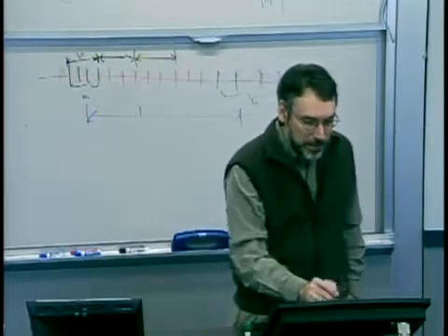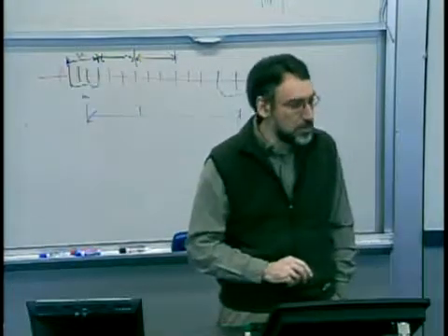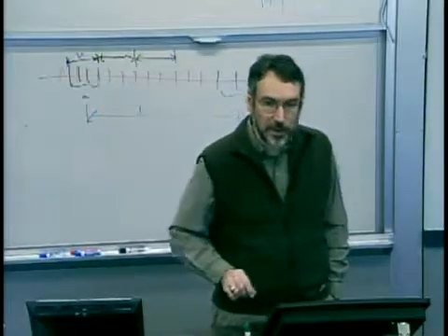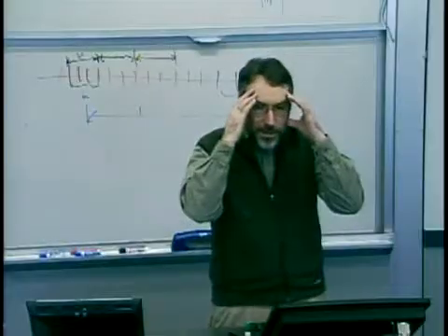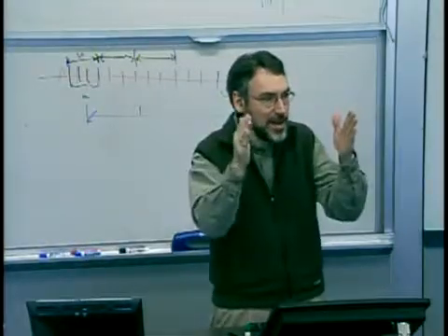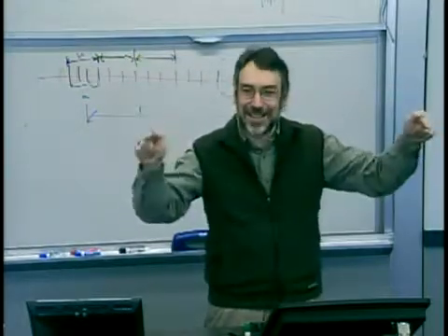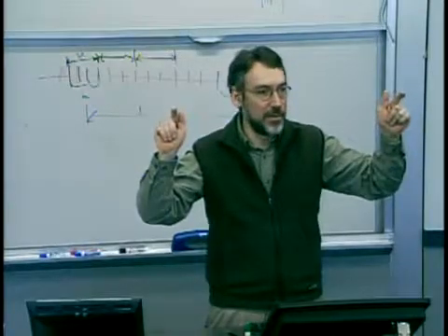So if I look at, first off, CP and CPK, my lower spec limit, upper spec limit, those are 6 sigma apart compared to the variance of my underlying process. That's just a CP of 1. So qualitatively, CP of 1, you should mesh in your mind, just says my spread is such that my plus minus 3 sigma tails are right at the spec limits, if I'm perfectly centered.